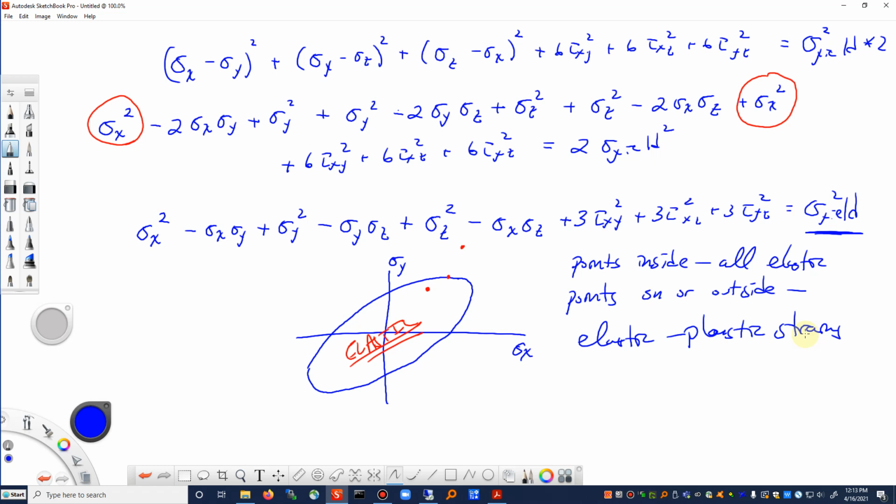Now, without getting into the details about deviatoric stresses, basically it is the stress tensor where we've subtracted away the hydrostatic stress, which is the average of the normal stresses. It leaves us with just the part of the stress tensor that is thought to contribute to yielding for most polycrystalline metals. The reason the deviatoric stress is very nice to use is that we have a perfect circle, a hypersphere in 9-dimensional deviatoric stress space, as opposed to a hyperellipsoid, and the geometry just becomes a little bit easier.